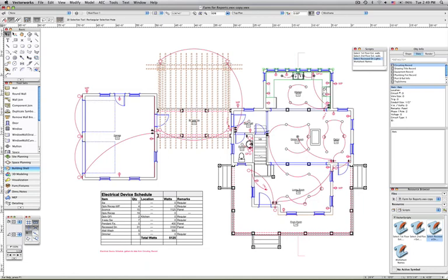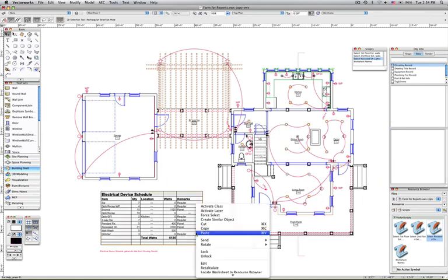I can then go back and edit the information to show how I might save some energy using compact fluorescent lamps rather than incandescent. We'll be able to see the number of watts decrease as I swap out the lamps, but also we should consider a decrease in cooling loads as well. I'll use a script to select all the recessed downlights on both the first and second floor, and by changing the number of watts used in the data pane from 100 watts down to an equivalent in compact fluorescent of around, let's say, 25, when we recalculate the worksheet, we can see we saved around 1300 watts.